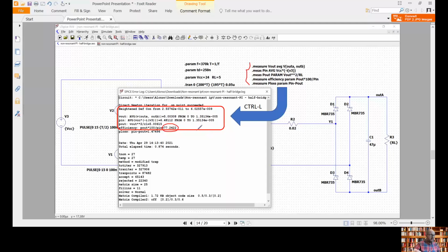But we have to take into account that this is a very low power system, it's only 5 watts. The current that is circulating here is about 1 ampere. So we have a lot of losses here. Most of the losses are in the output rectifier, because we have here the current of 1 ampere within half semi-period, and usually the voltage in the Schottky diodes is around 0.4, 0.5 volts.